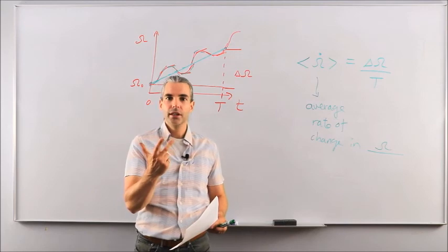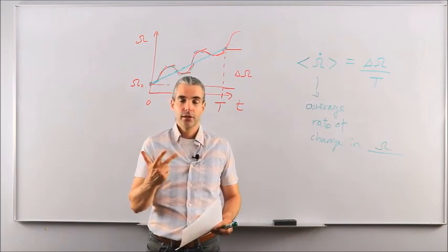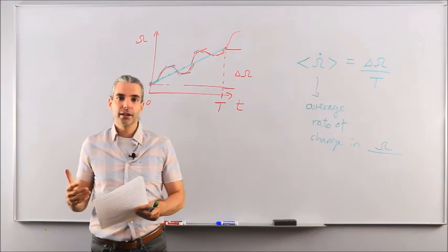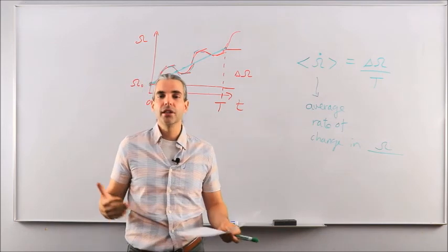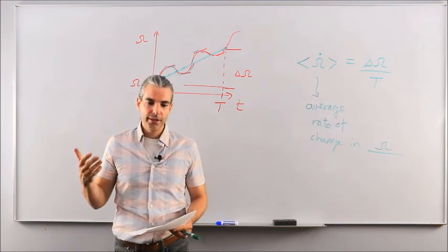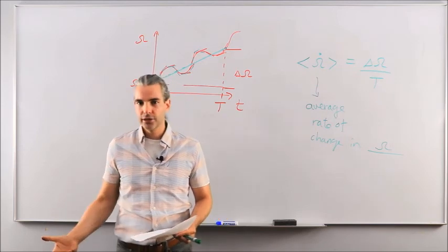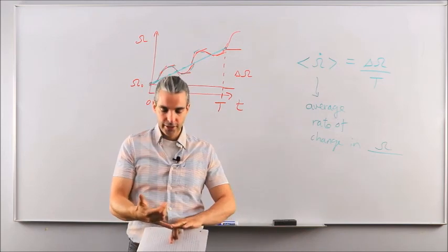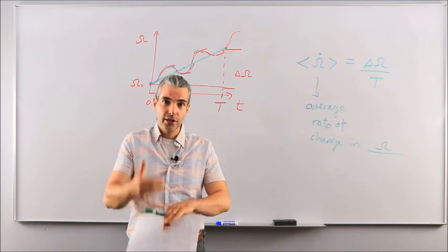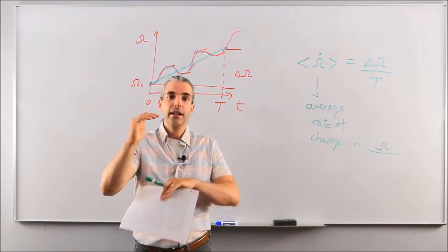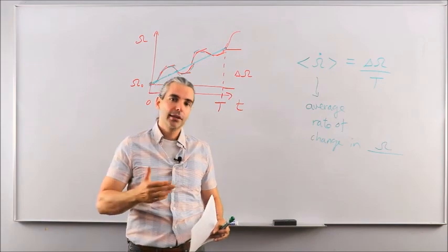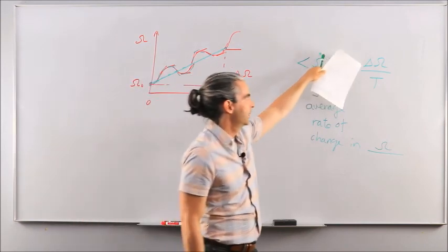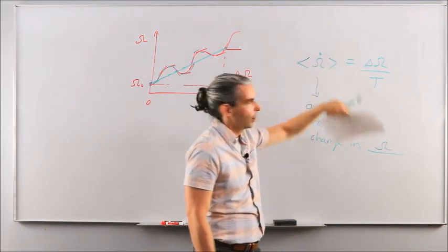And once we have those 3 components, or those 3 scalars, all we need to do is to plug these back into our Gauss Variational equations, which will allow us to predict at what rate our orbital elements vary as a function of time. Those were the da/dt, de/dt, di/dt, and so on equations. And then based on that, we can go 2 steps further. The first step is to look at the secular variation, which is the net change in a given orbital element after one orbital period. And then we can take another step, and that is to look at the average rate of change in our orbital element by simply dividing the secular variation by one orbital period.